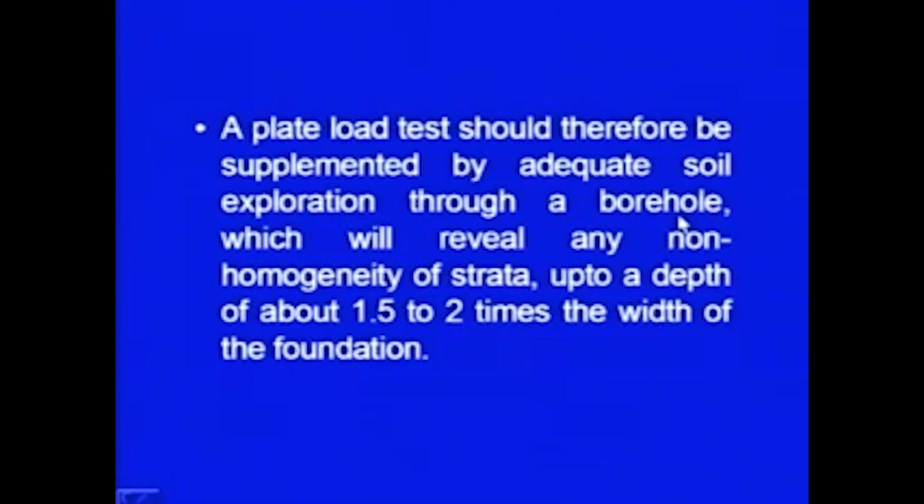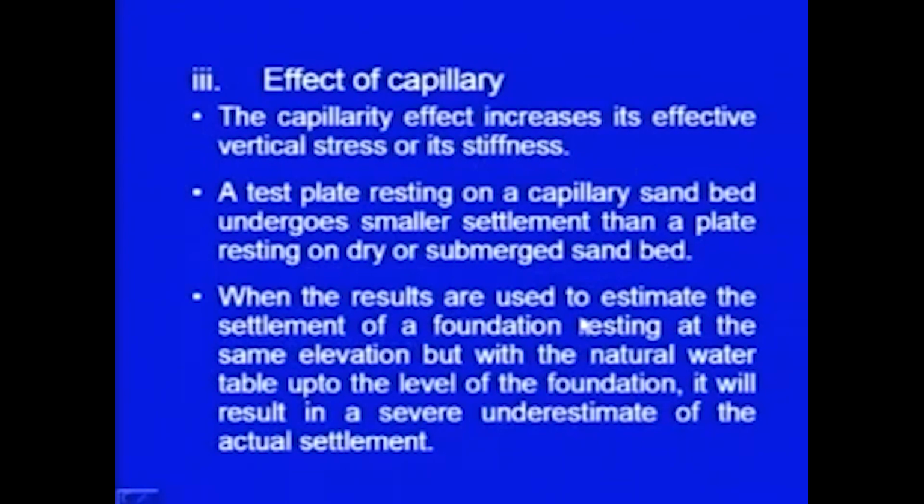This is in fact true for any field test. What we recommend is you should not rely on one particular test, but there should be confirmation by different tests. The plate load test should be supplemented by adequate soil exploration through a borehole, which will reveal any non-homogeneity. If it is a homogeneous soil up to a depth of about 1.5 to 2 times the width of the foundation, this is the effective depth. This is the depth which will be contributing towards the settlements, in case of the sandy soils. So, if that much depth is homogeneous, you can rely on these results. If it is not homogeneous, then we have to do some other tests.